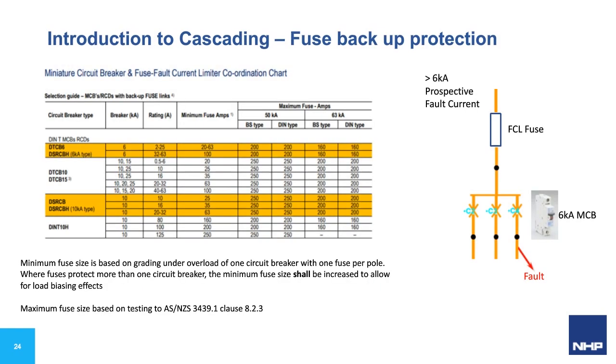Fuses are very effective fault current limiters suitable for some applications, especially where fault levels are high and sub-circuit current values are low. The current limiting fuses operating in their range will limit the maximum instantaneous peak current within the first half cycle to a value substantially less than if the fuses were not in the circuit. The peak value is almost always well below the prospective RMS value, and the energy let-through is also minimum. The compromise is that the fuse always needs to rupture or blow to deliver the result, and as a consequence will interrupt power to all circuits downstream.